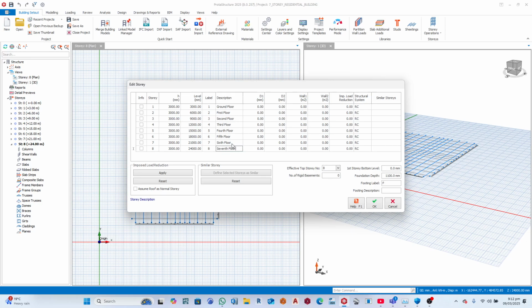So we adjust the floor heights from here. So I would like our ground floor to be the tallest. Okay, so maybe we can give it, what do you think, 4.5 meters, 5 meters, maybe 4.5 meters.